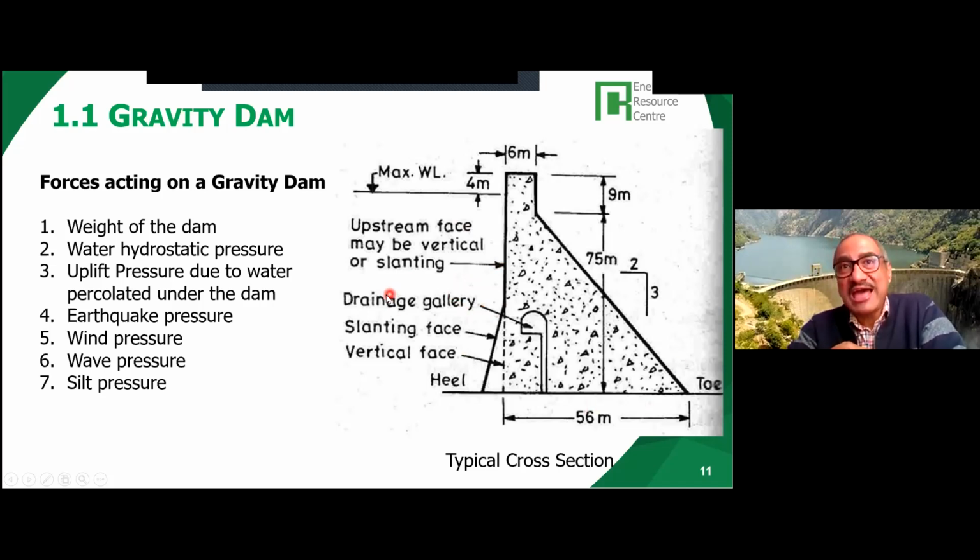Some people also have a bypass tunnel where you can do the flushing of the sediment. But these are very complicated design proposals, and I don't know how successful they have been, but there have been plans like that. Sediment management is a big issue for dams, and there is serious criticism by environmentalists and social organizations of dams, considering the problems dams face with sediments.